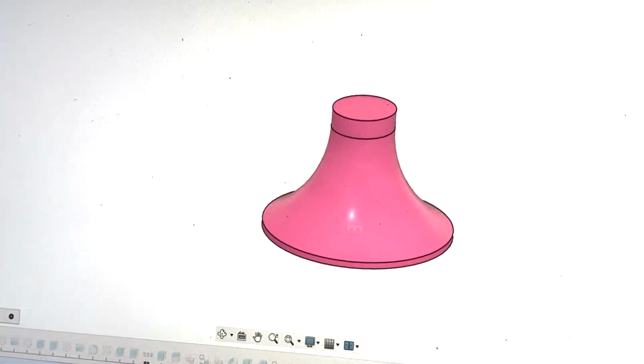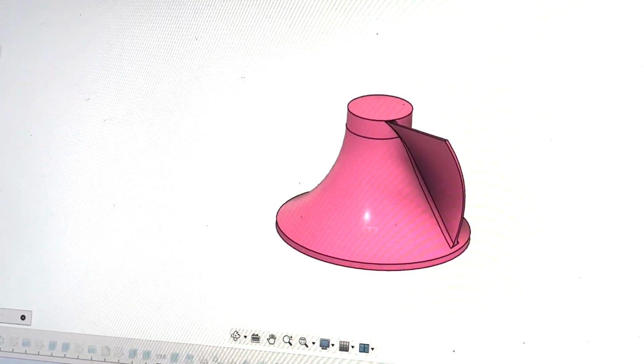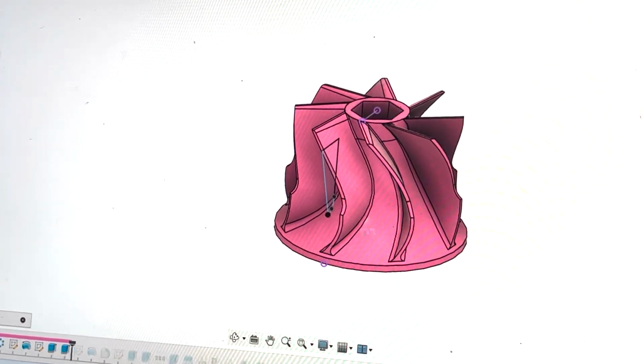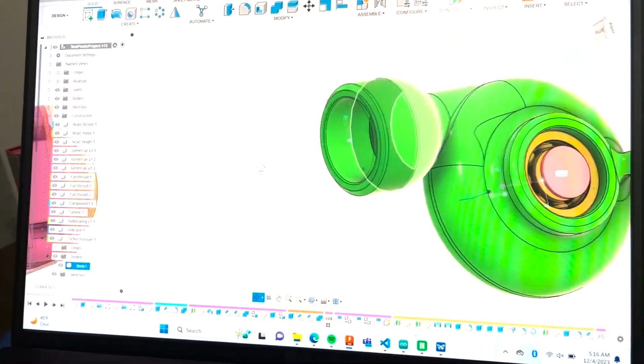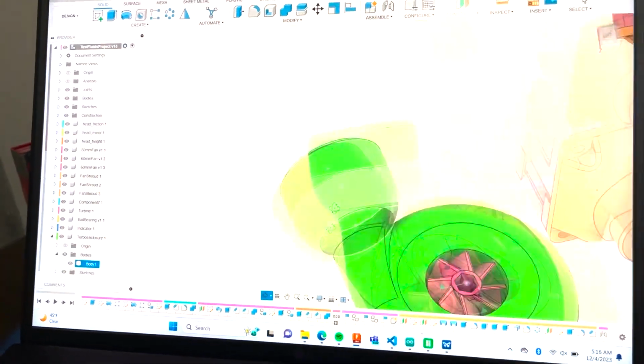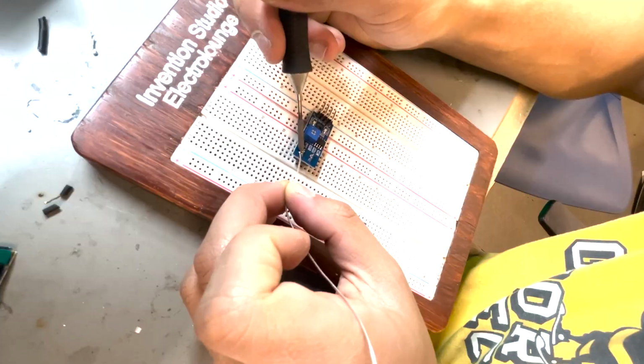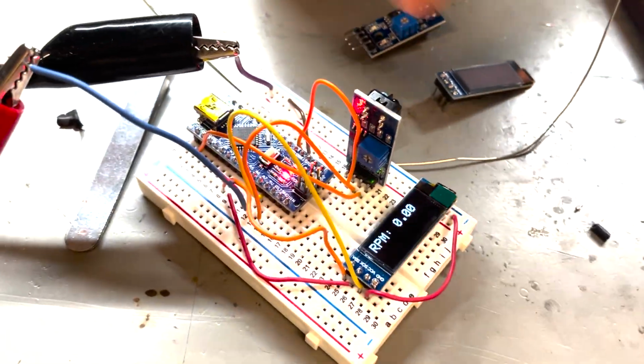In terms of measuring airspeed and keeping the apparatus relatively affordable to make in a reasonably sized package, we decided to make makeshift anemometers, with turbines inspired by turbochargers and IR sensors measuring RPM. After a little bit of manufacturing, which included traditional FDM 3D printing, resin printing, water jet cutting, metal brake bending, press fitting, soldering, coating, and testing, we made a thing.